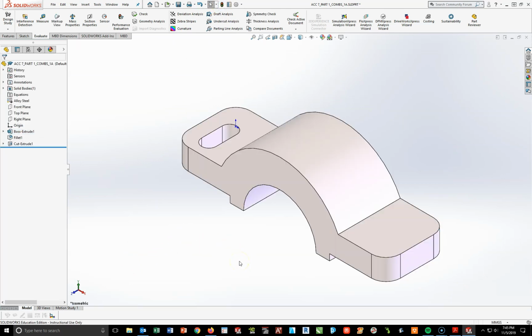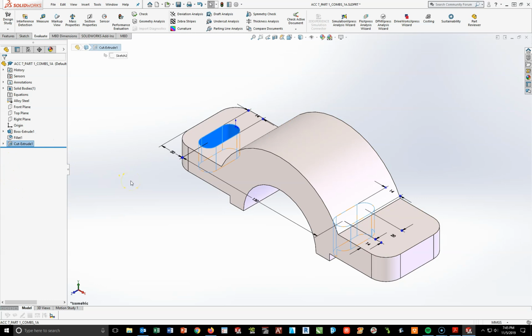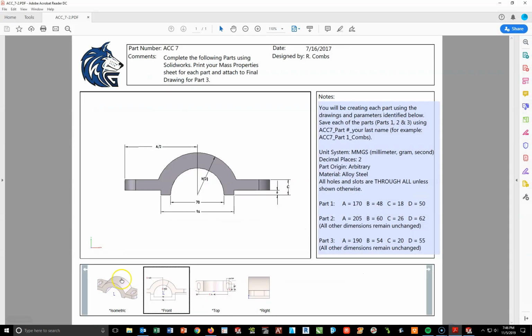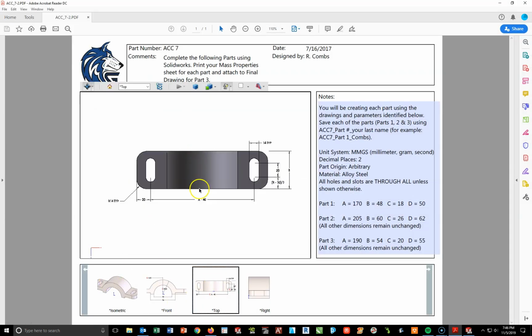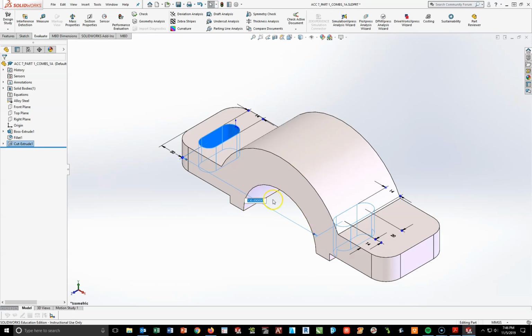Now, your first panic may be, oh no, I lost one of my slots. It's okay. It's shifted. You've got to remember, these numbers have changed. The 20 will stay the same. The 14 stays the same. But this 130 changes from 130 to A minus 40, which is 205 minus 40. So going back to this, I'm going to put 205 minus 40, enter.